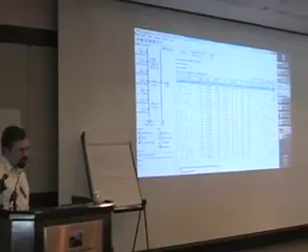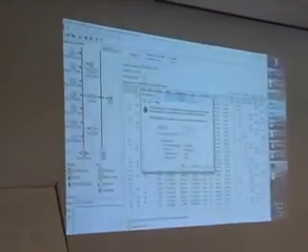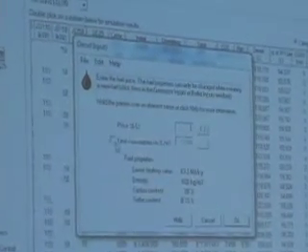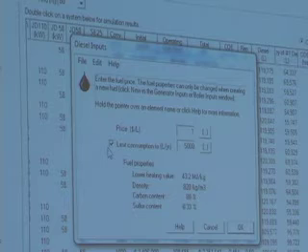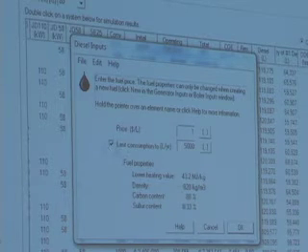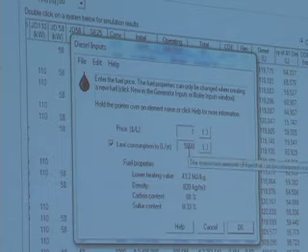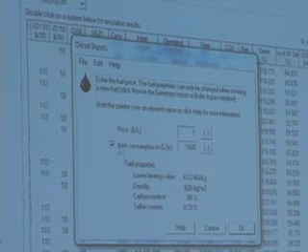Say here you can build a fuel, in other words, ultra low sulfur versus DS. Yes. So let me show you how to do that. And that's a really good question, actually, because it's not totally obvious. The fuels are down here, and here's where you can change the price of the fuel. So we were assuming $1 a liter. And we can also tell Homer, add a constraint here that says, design me the least cost system that uses no more than X amount of fuel. And we could do a sensitivity on that. But that wasn't the question.